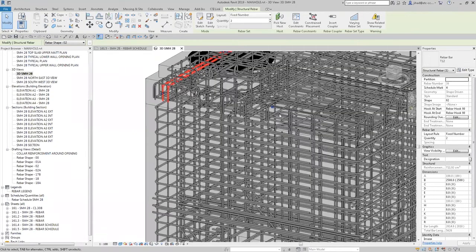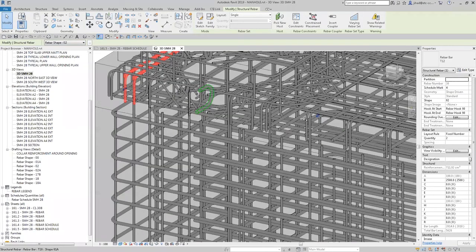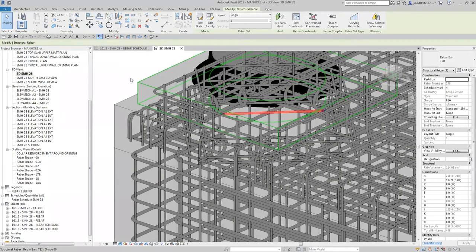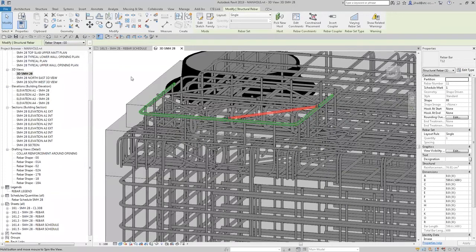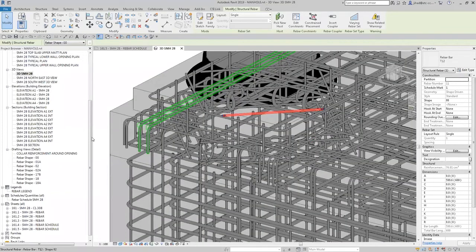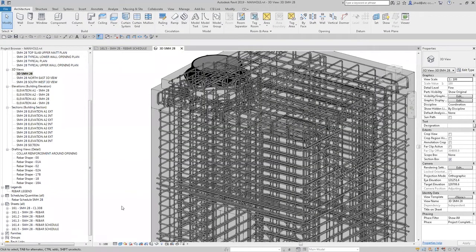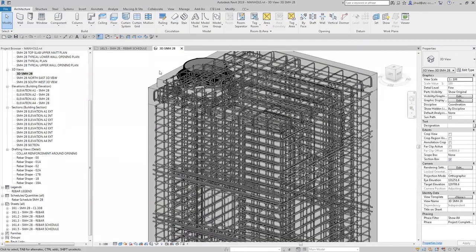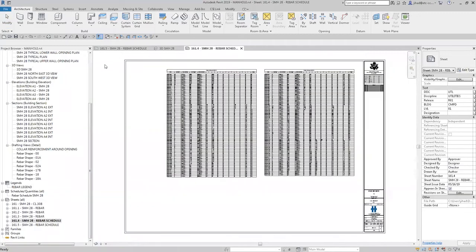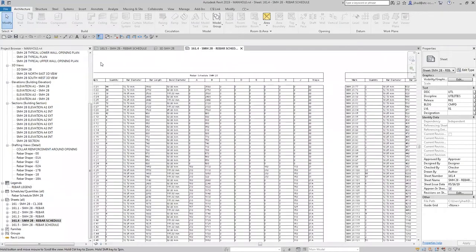Our job is to ensure that this work is properly accomplished, and Revit helps in ensuring that all is done accordingly, from iron professional placement, to opening reinforcements, and most importantly, having a correct and well-made bar bending schedule, that helps the blacksmith operate in an efficient and thorough way, with minimal time and slightest iron waste.